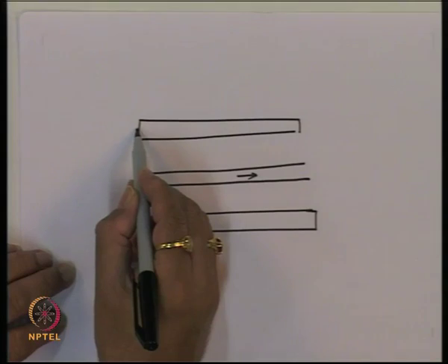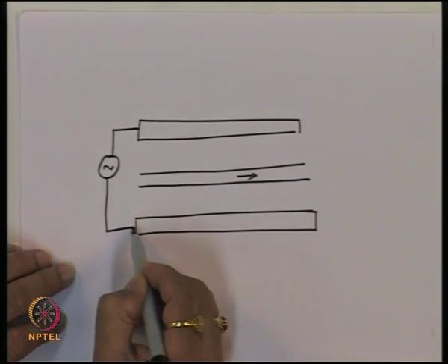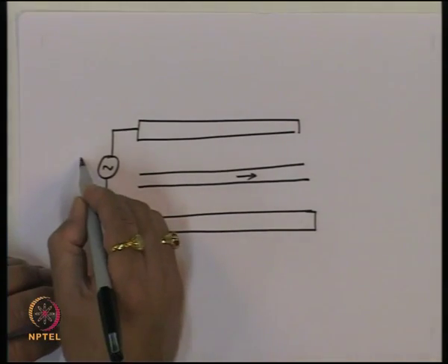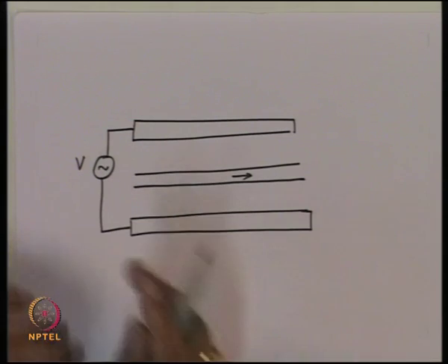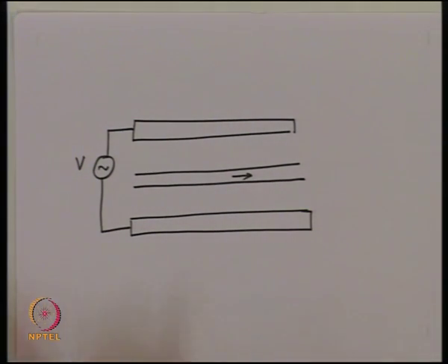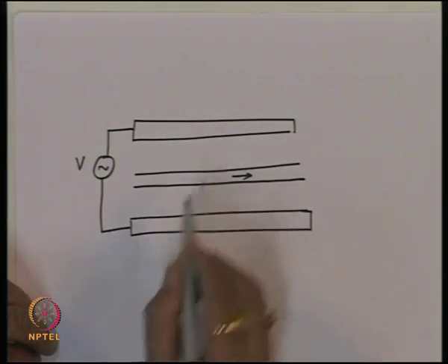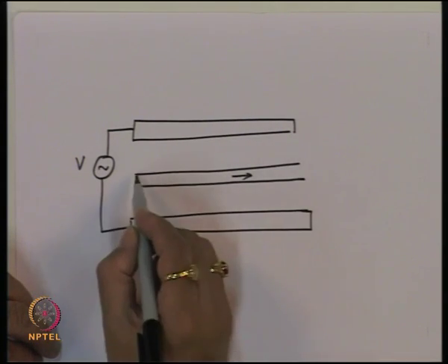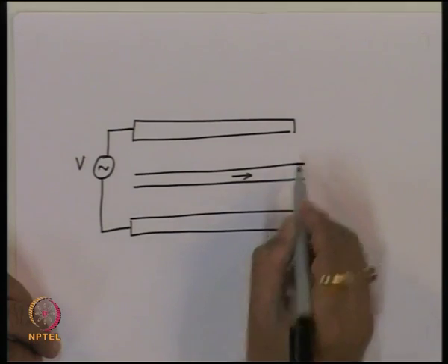So we can connect a signal between these, which is the signal which you want to apply, the voltage. And since we are having this voltage at reasonably high frequency, like few gigahertz, there will be a signal traveling on the structure with phase velocity, and the light will be traveling inside this in the channel waveguide.